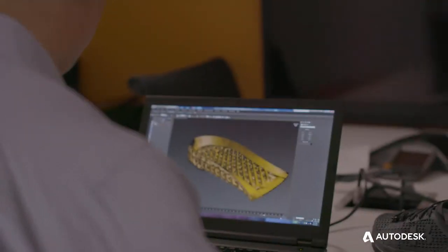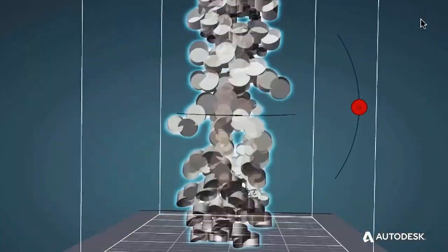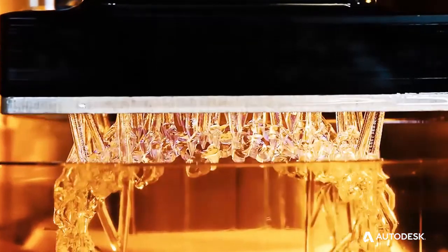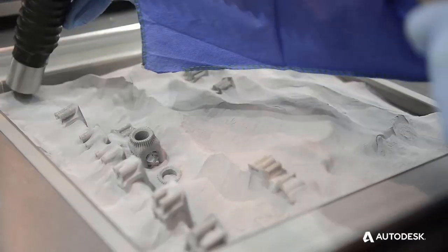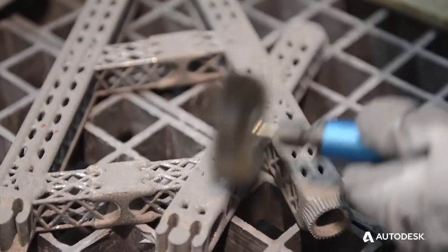In a medium shop, there are professional-level additive machines that have large build volumes, use several materials at once, and print a separate support material, which allows for more complex geometry. These can also be FDM and are sometimes stereolithography, or SLA, where a liquid resin is cured using a projection of the layer geometry. At the highest and most innovative level of additive manufacturing, selective laser sintering, or SLS, can be used to make parts in plastics and metals by using a laser to solidify a powder into solid parts.